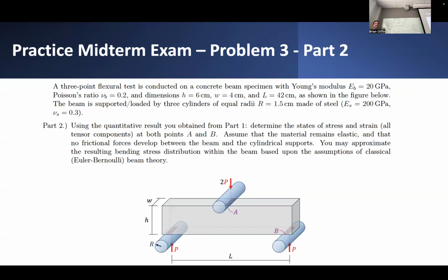Well, you can figure out in a few different ways. You can go about solving this simple beam equilibrium problem. You can solve for the resulting shear and bending moment diagrams. But what you'll find is that this should have a value of PL over 2, something like that.